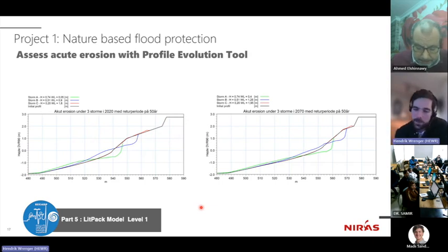But again, we will come up with answers to those questions during this modeling campaign, but still need to be aware that we will likely have made mistakes. There will be mistakes in this whole modeling chain. It started with the spectral wave model. We use atmospheric forcing. In that atmospheric forcing, maybe the islands were not resolved correctly. So we don't have the winds 100% right. So we don't have the waves 100% right. We might not have the bathymetry 100% right. So there are all these accumulated